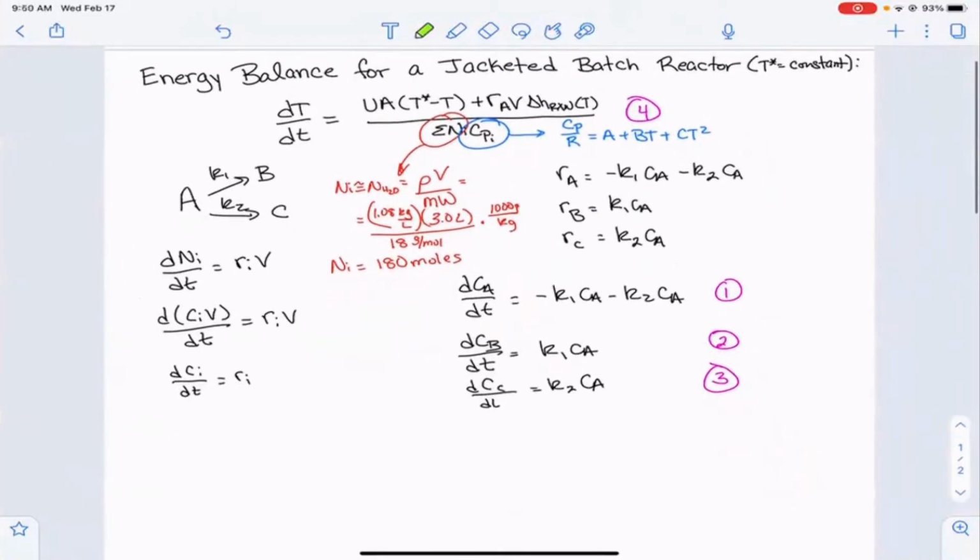We also have to remember how temperature gets implemented in our reaction rate constants. And so for either of these, remember that ki at some temperature is equal to ki0 times the exponent of minus Ea for that reaction divided by RT. And so if we were looking for two different conditions here, well, we're not actually given ki0 in this problem statement.